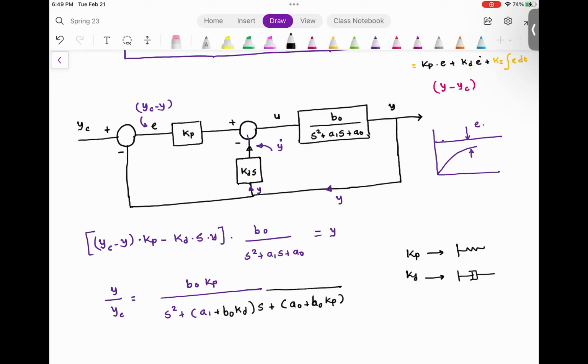So if you were to derive this equation using a KP plus KD type of transfer function, you will get an equation in the same form, but from the implementation point of view on aircraft dynamics, you will notice that the controller loop is implemented something like this.